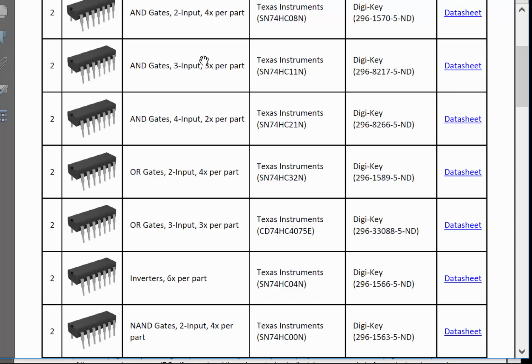All right. Then you get finally to the OR. And here's the problem with the OR. The OR is going to have 4 inputs. Now, why is that an issue? It's because you don't have a 4-input OR gate. You only have a 2-input OR gate and a 3-input OR gate. So now you have a situation that's called fan-in. Okay. You don't have enough inputs into the gates that you have to implement what you want. So you have to figure out how to address fan-in.